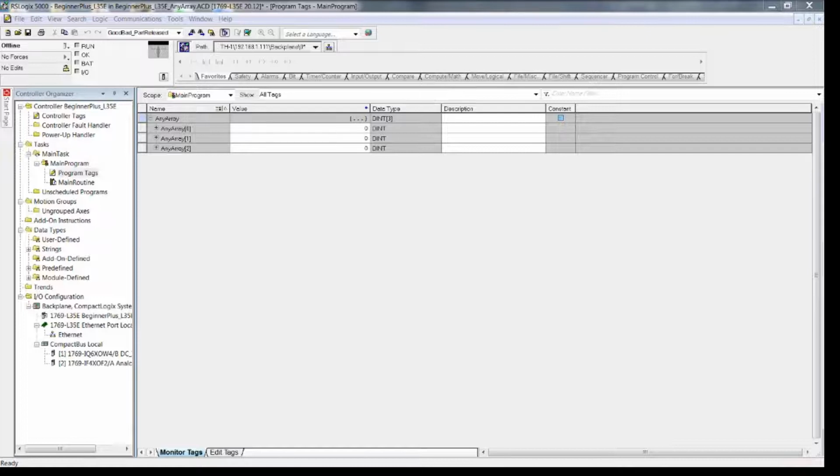When the bits shift left, the most significant bit value moves to the least significant bit position of the next highest double integer in the array. The least significant bit of the lowest double integer sucks in a 0 or 1 from the source bit. And the most significant bit of the highest double integer pops its value out to wherever it came from.